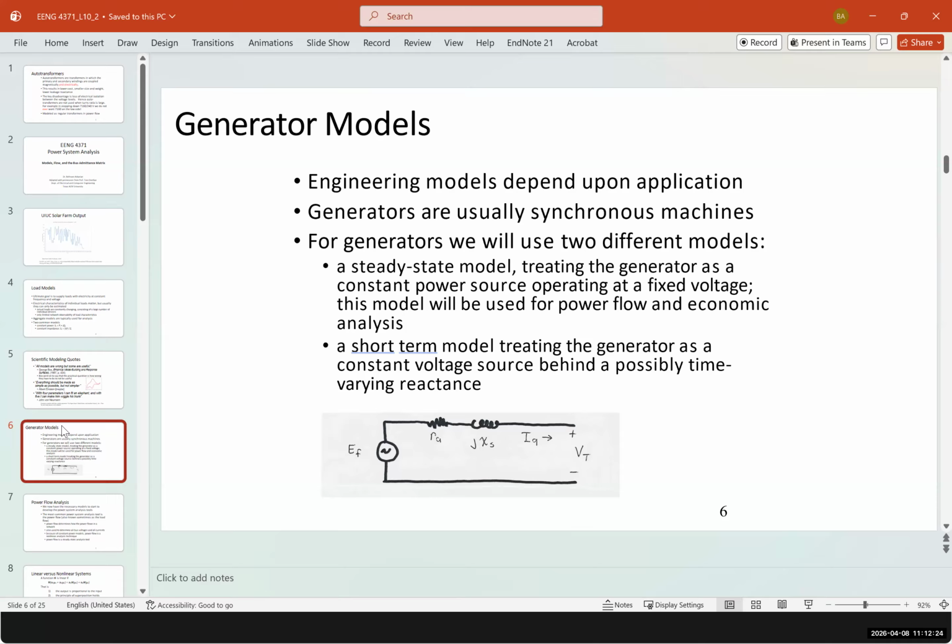But in a solar system, because it's all electrical, there's no mechanical part where you have to open the valve and wait until it increases. In an inverter, because everything is electronically controlled, it's done in a fraction of a second. And also you can perfectly match the phase as well. For a generator to match the phase, sometimes it takes half an hour or an hour.